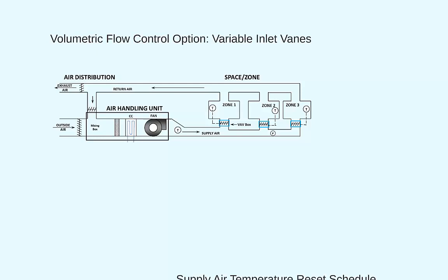The location of such a sensor is usually determined by the TAB, or Testing, Adjusting, and Balancing subcontractor during the balancing process, and it is typically 2/3 to 3/4 of the way down the supply duct run. We will impose a pressure set point we want the system to maintain. So, if the VAV dampers close a bit and the pressure rises above that set point, we will have a controller send a signal to some mechanism that will now change the fan operation to bring the pressure down a bit. During the hydronic lessons, we only discuss the use of the VFD to perform this function. And we will talk about the use of VFDs in air systems here in a second.